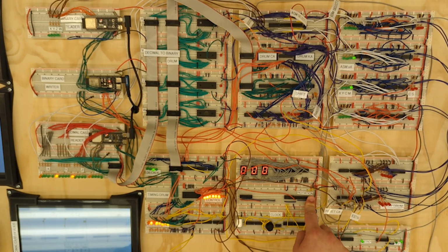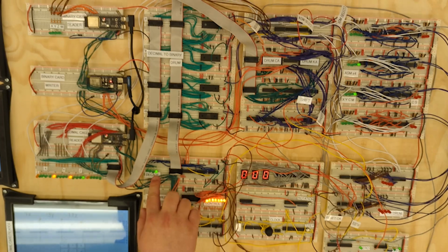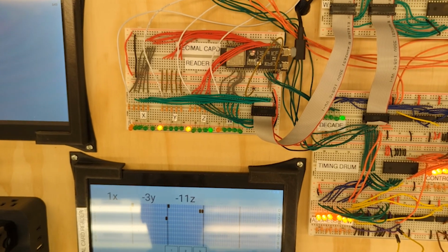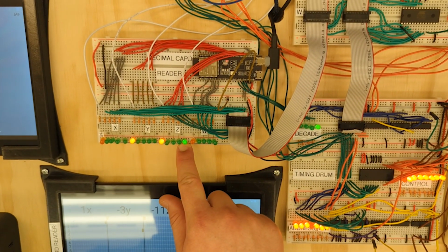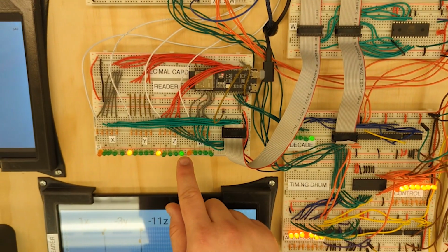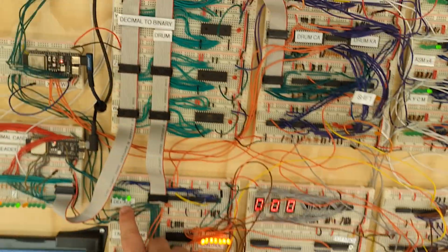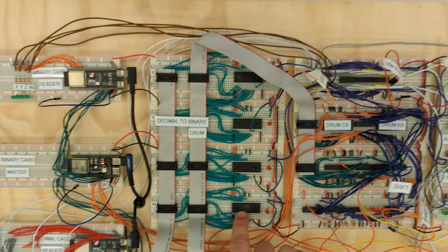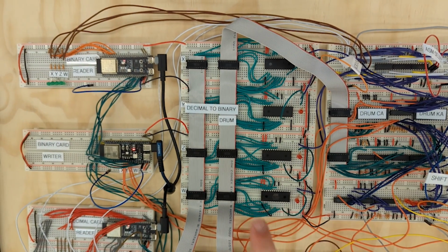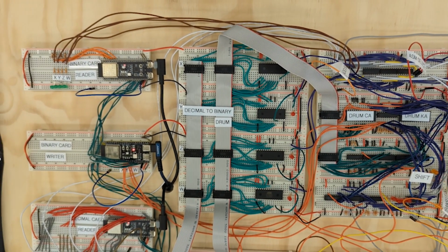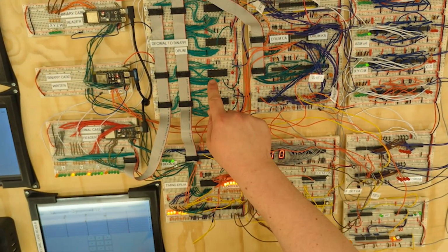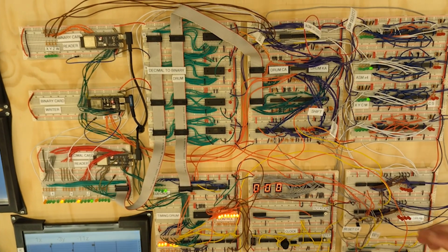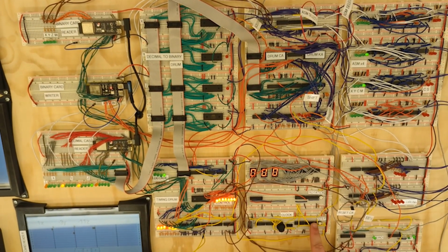Okay, let me finish out this cycle here. Now that we're at this first decade, we're going to get the 10 part of the 11 loaded into the machine. So we have this bit here of z asserted because it's a 1. And that is going to combine with this decade and this address from our timing drum as an address into these EPROMs, so that this EPROM specifically will output a binary representation of 10. Then that binary representation of 10 will be subtracted from 0, since we're subtracting, and that'll give us a value of negative 10 stored on the drum.